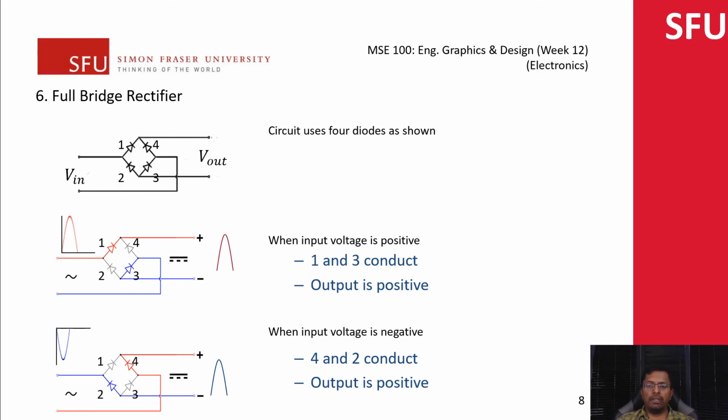If I connect all of these, you're going to get this pulse and this one, because the sinusoid is a repeated sequence of positive and negative pulses. Each of those gets rectified, and the output is going to look something like this over here. So you just flip all of those sine waves, and you get a rectified signal, which is a full wave rectified signal.